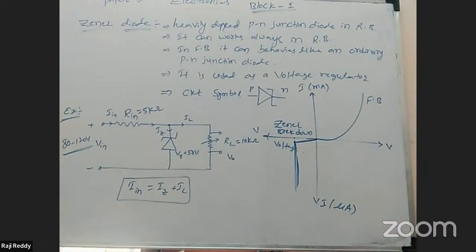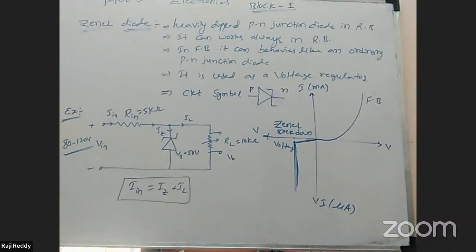VVC is called a voltage variable capacitance diode. As semiconductor materials, it depends on voltage and its capacitor values depend on it. Their mode of operation depends on the capacitance that exists at the PN junction when the element is reverse biased.